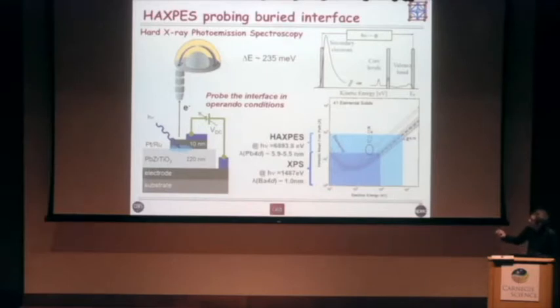The inelastic mean-free path goes up to about 10 nanometers, and basically that means you're getting information from the first 25, 30 nanometers. So you can see through a top electrode, a realistic top electrode, not some ultra-thin thing which is discontinuous and is probably not even a real metal, but something like 10 nanometers. It's reasonable, it's continuous, it's going to screen as a technological electrode would actually do, and you can look at this interface providing that there is a distinctive chemical signature coming from that interface. So that's what was done.